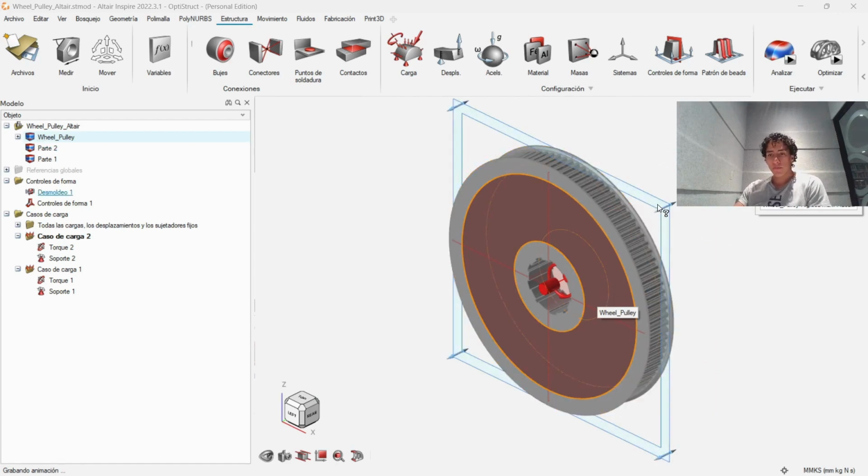For shape control, I added a double draft which has a demolding direction from the central plane parallel to the part towards both outer sides. The goal is to concentrate the material in the center and make it easier to 3D print. I also applied cyclic symmetry control to achieve a pattern repeated 4 times around the part, providing a visually symmetric shape.